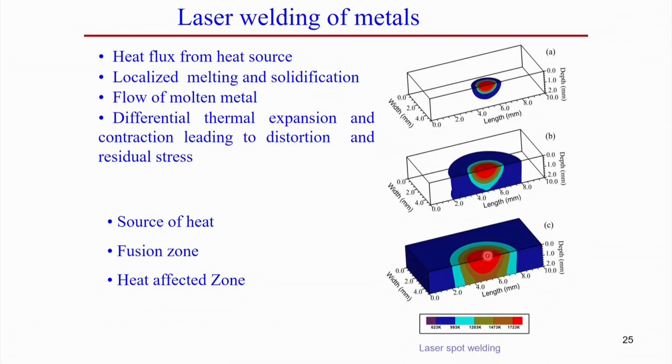So, within the simulation process, apart from the red color, the other different colors we can produce are the contour isotherms, that means constant temperature. That temperature actually indicates the heat affected zone in case of the laser welding processes.